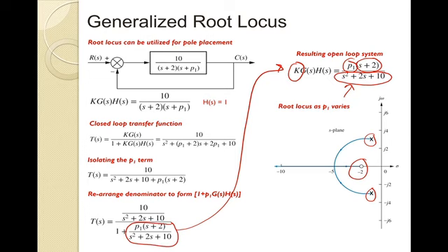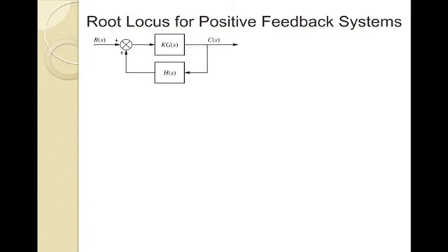And then as we vary P1, remember what's going to happen. So K equals 0, we start at the poles, and then notice the trend. It's going to go away from the poles, hit this axis, and then go towards this finite 0, and then this way off to this sort of infinite 0 over there. So now, again, we could vary that as a function of P1 and get a desired characteristic for our system that is, again, whatever our goal is for that system.